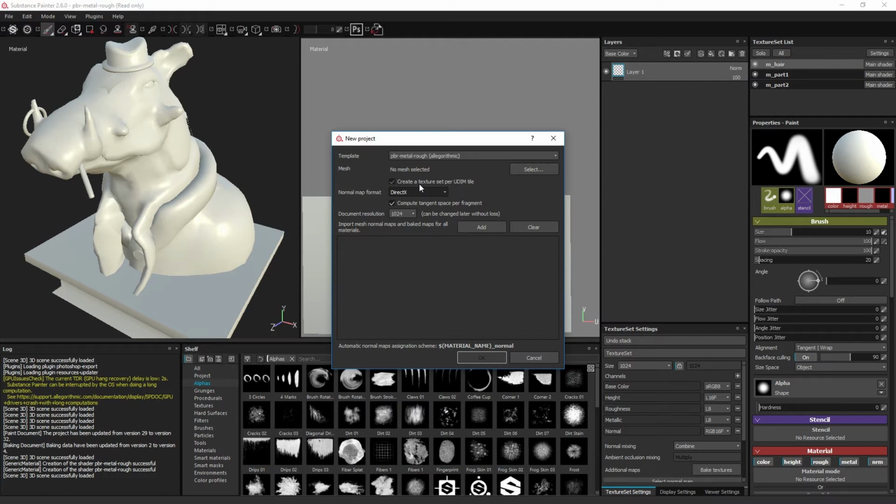For instance, instead of working on a 16K by 16K texture, an artist can instead work with 8 2048 by 2048 textures without creating 8 different materials and cluttering the material hierarchy. Painter will create a texture set for each UV range that has a UV island in it. So in this case, it would create 8 texture sets. Not all rendering environments support it, so you will need to look that up before deciding on using this method.